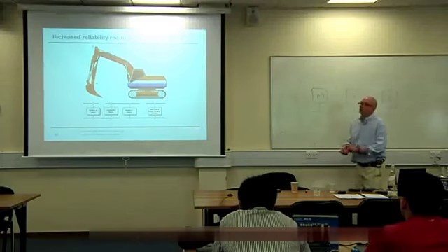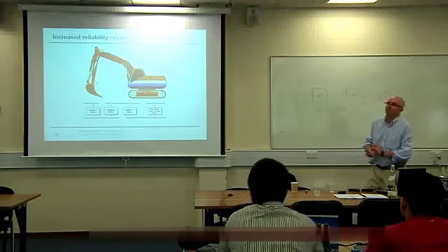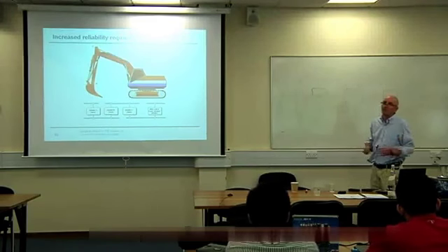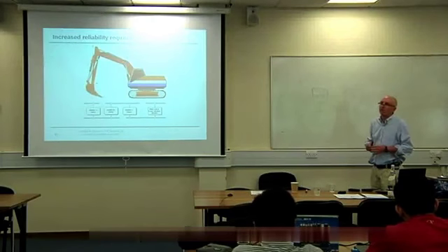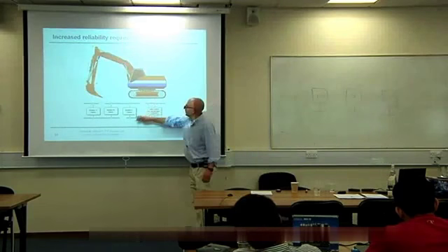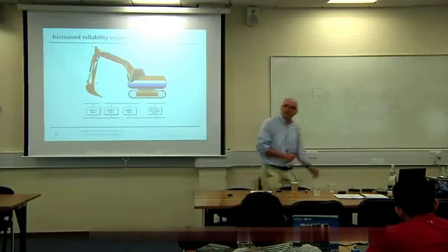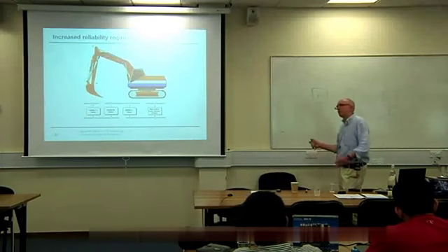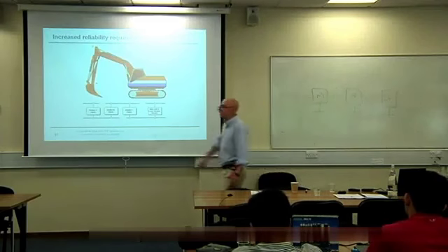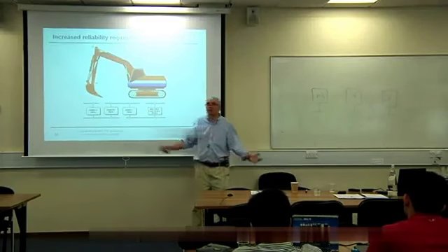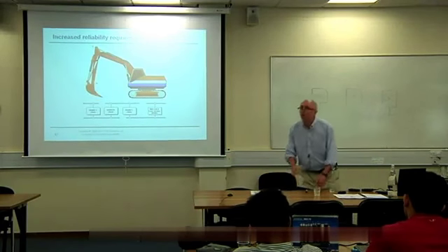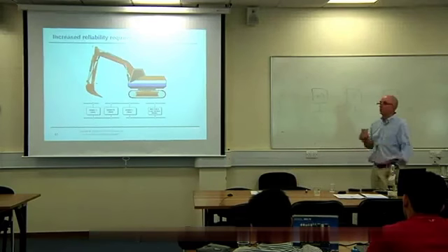Suppose the network is shorted. If the network is shorted, in most cases, the whole bus becomes inoperative. So if you cut it, that's comparatively straightforward. It's not good, but it's comparatively straightforward. If you short it, it's not that simple. I short it here and I short it here, I've lost the whole lot. What do I do? What's wrong with my basic network topology?